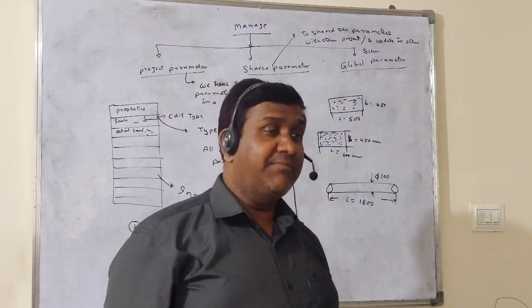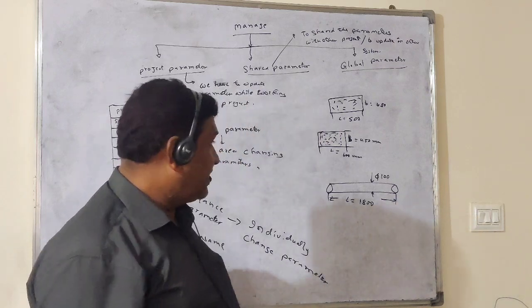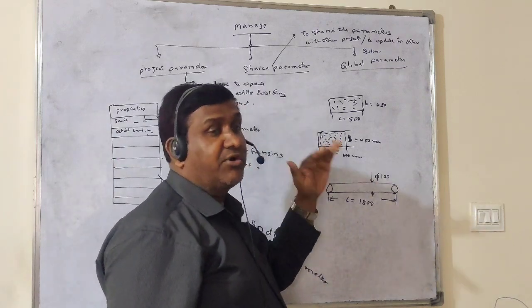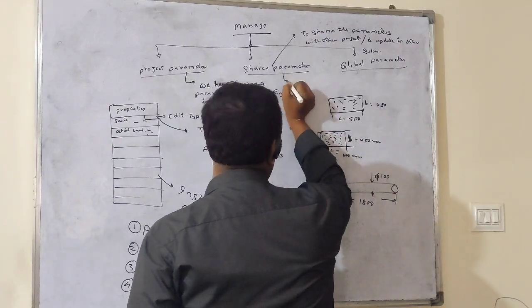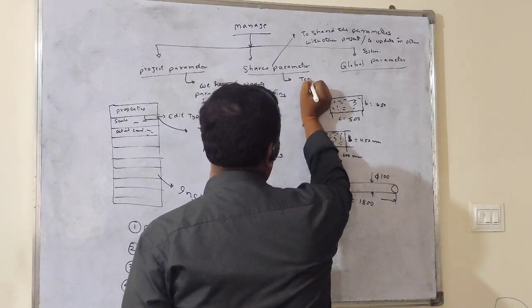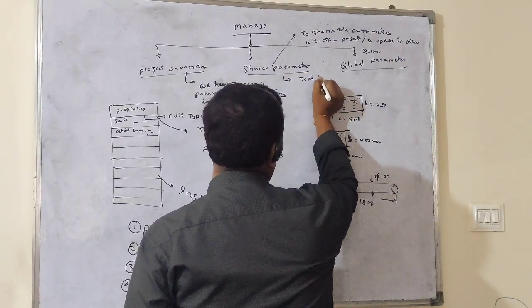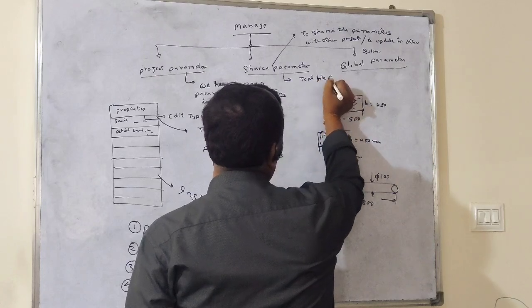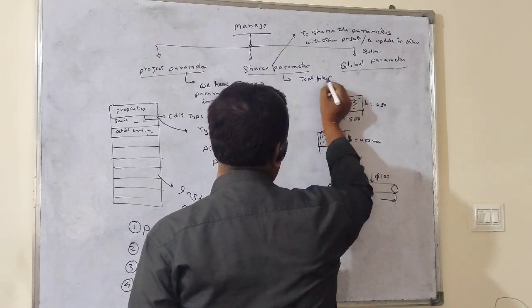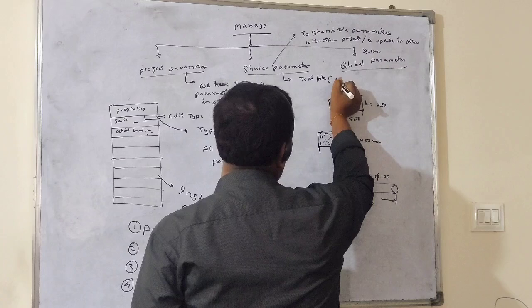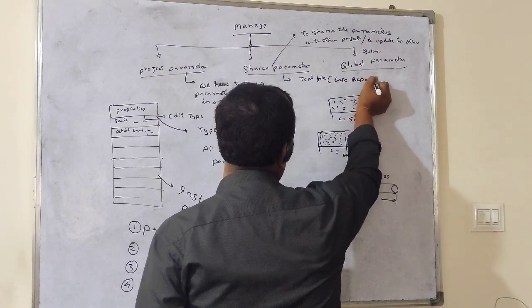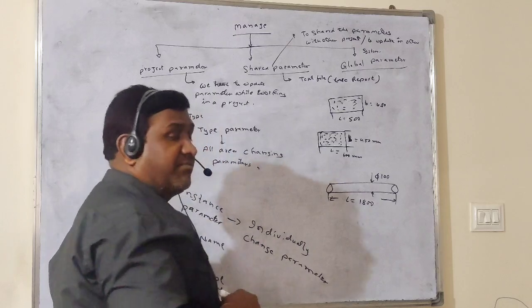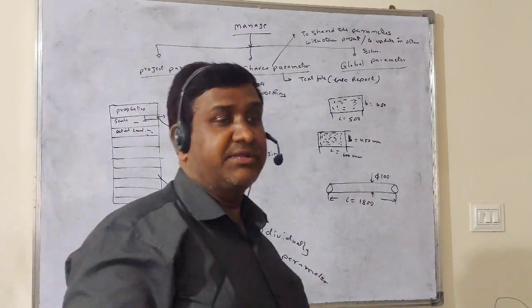So however many times you create new things, it is updated the same, because in shared parameters we can take the parameters separately as a text file. It becomes a text file, and we can take the report from the shared parameters.